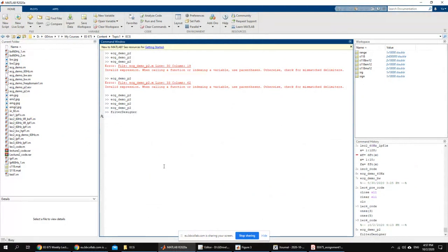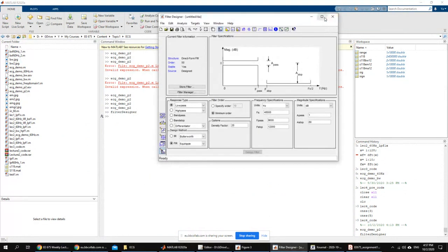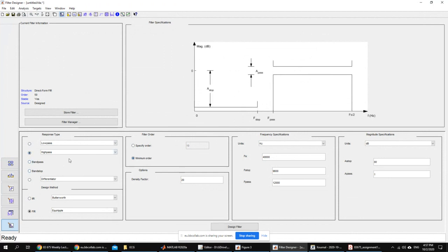Okay, the one that we used before, and try to make sure that 0.1 hertz is basically in the stop band. We said, let's show the filter that we actually decided that we will use. It's a high-pass filter. A high-pass filter looks like this. It basically starts from a certain frequency. You have a pass band frequency here. It passes all frequencies above that, and it attenuates the frequencies below that.